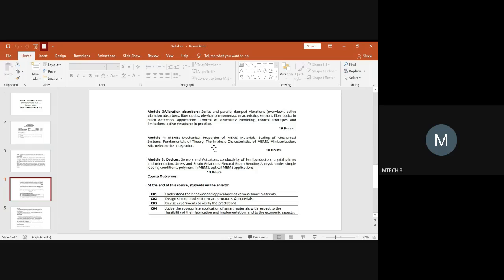If you want to go with photolithography, then you will be explaining how you make a MEMS device by the photolithography process through photoresist. Photolithography is pattern generation on the substrate. So you have to explain all the steps in fabricating a MEMS device.